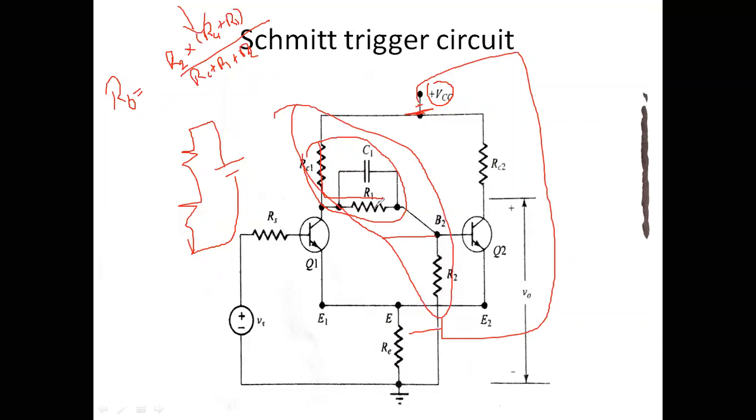Therefore, in this circuit, you are going to find out. These two are in series, and R2 is separate. Therefore, simply I can apply voltage division. I want the Thevenin's equivalent voltage here. That is, the voltage before subtraction is VCC, and we have to find out the voltage across R2. Therefore, that branch resistance R2 divided by total resistance. Total resistance is nothing but R2 plus these two series combination, that is R1 plus RC1. Therefore, we have found this is your Thevenin's equivalent voltage.